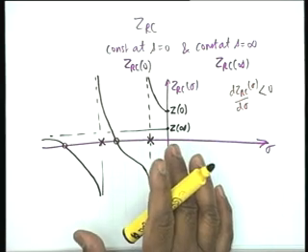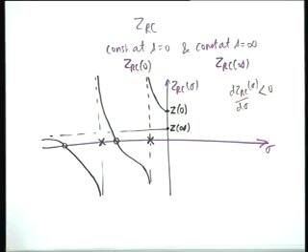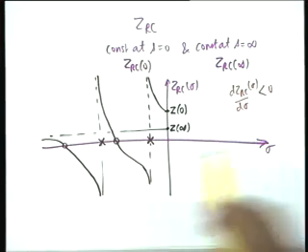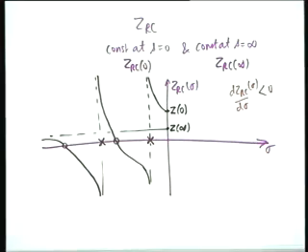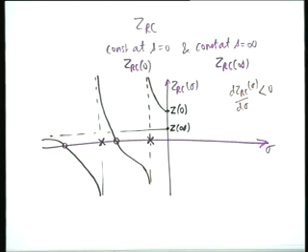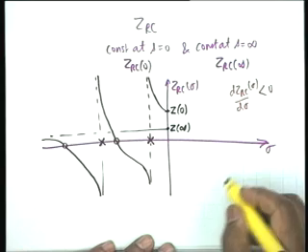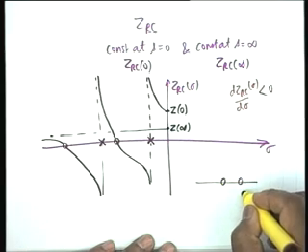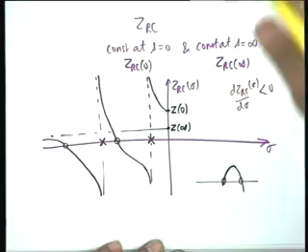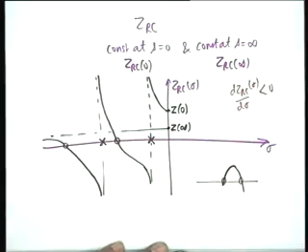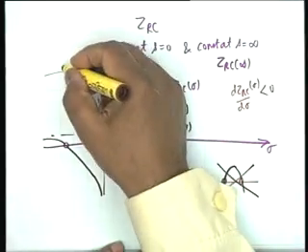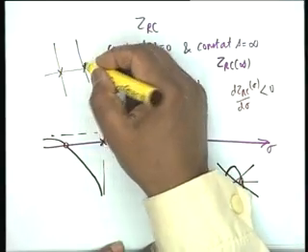The message that we get from here is, first, poles and zeros must alternate. We cannot have two adjacent poles or two adjacent zeros. Why not? Because then the slope will not be strictly negative. If there are two adjacent zeros, for example, then it must go up and then it must come down. So the slope has to go through 0 and then positive, which is not permitted. Similarly, we cannot have two adjacent poles.